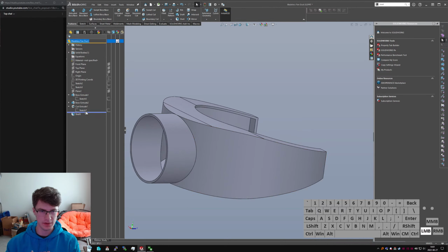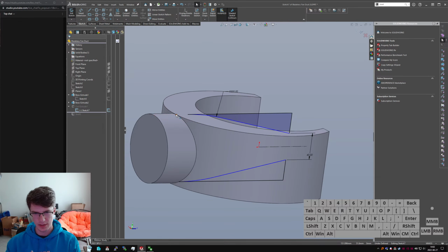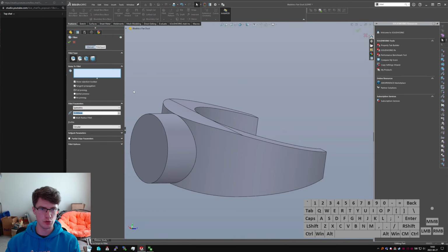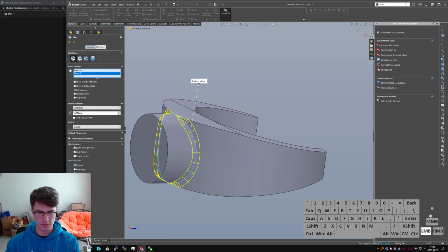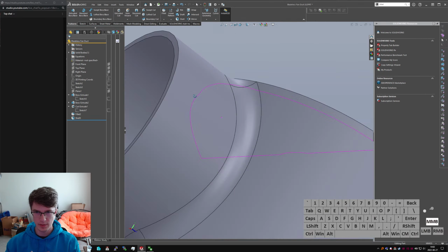Should probably fillet it first, just for safety's sake. And here's one thing, actually, now that I'm realizing I'm curious about. If I make that coincident, and it complains again in the shell feature, what if I instead just add a huge fillet? Like, well, maybe not huge, maybe just 10 millimeters. Do fillet options, keep surface. Well, let me do that. Well, not. No, keep edge. Or default, I suppose. Hey, check that out. It will play nice.